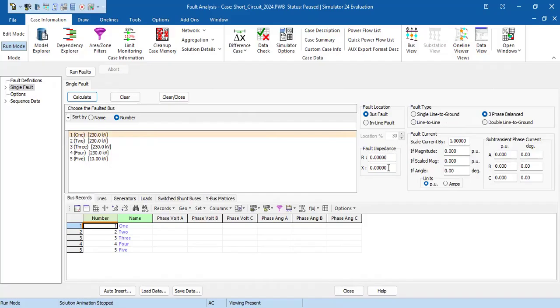The fault impedance, you wouldn't check this for now, but if anything, this basically says that let's say it goes to ground, but say it connects to a tree. The tree can have an impedance. Remember, the word impedance means it has a real and imaginary part, right? So I would call it an R and an X. So let's say it connects to the ground through the tree. The tree has an impedance, so you call it a fault impedance, which is just an impedance on the pathway to ground. Normally they will just assume this to be zero, but in reality it always has a fault impedance.